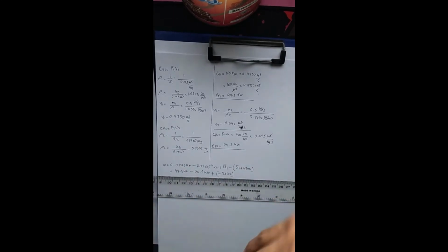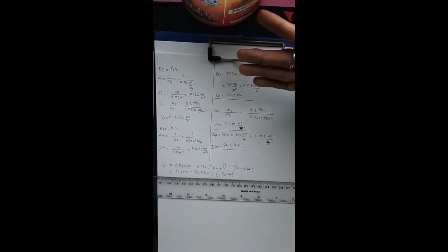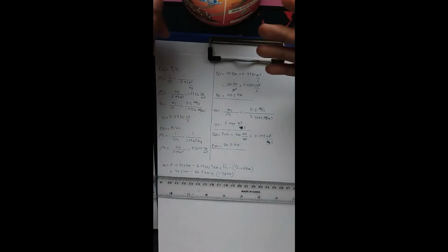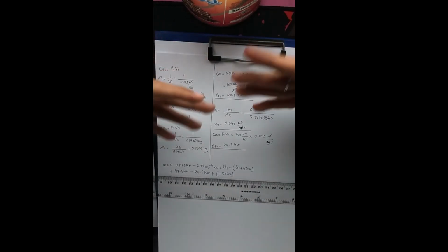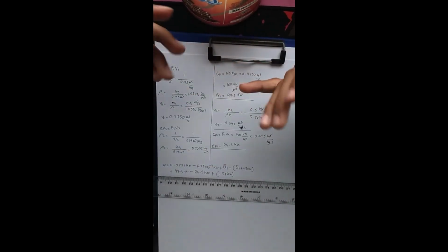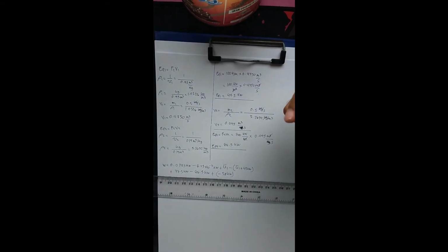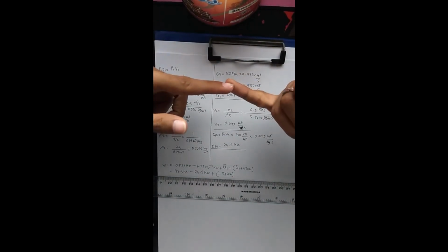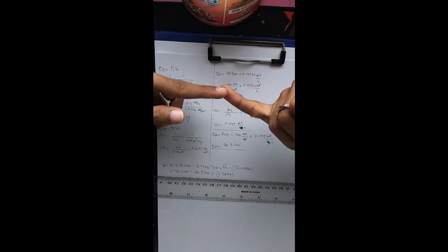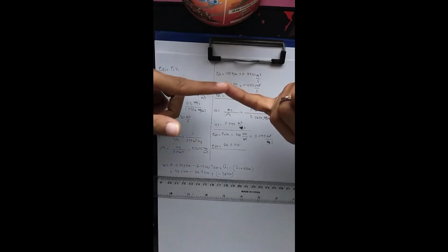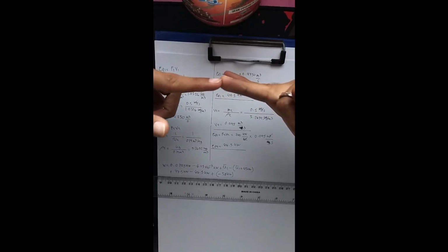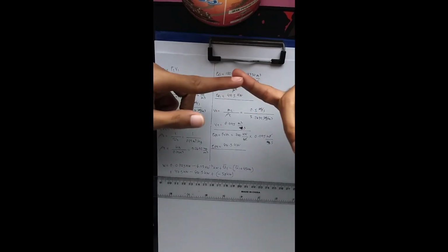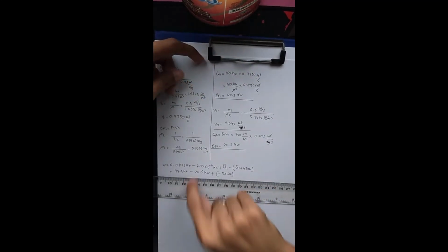And here's the thing, there's actually a clue in which you are going to be able to know if you are correct or not. If ever you are solving for compressor problems, air compressor problems, the heat should always be negative, because a compressor rejects heat and also receives work. So therefore negative heat and negative work.